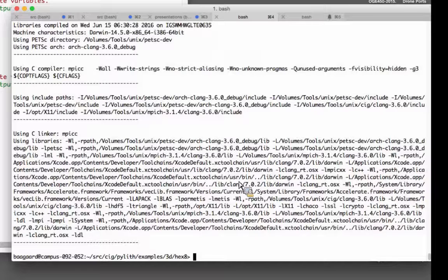You can think of slip as relieving the stress on the fault, so we slip it a little bit and look: did we slip it enough or too much, based on the fault tractions for that amount of slip? Then we adjust accordingly and repeat that process until the Lagrange multipliers are equal to those allowed by the friction model within a given tolerance.